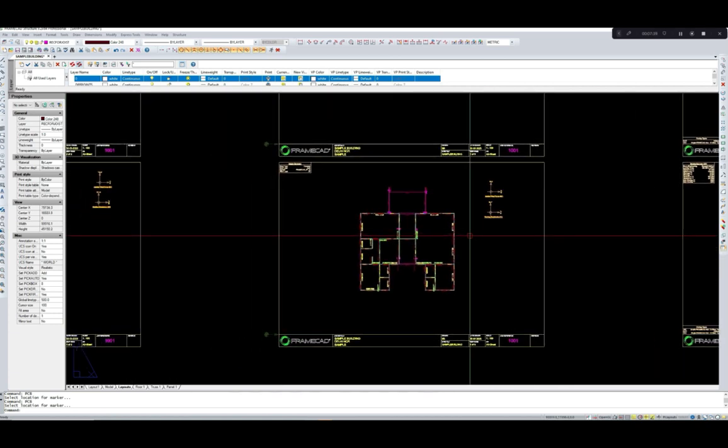See, at times for this building the resistance provided by the strap braces and the K braces is enough, but at times we must include the resistance provided by the mild steel structural frame, so that whatever is deficient can be covered by the lateral resistance provided by the mild steel structural frame.